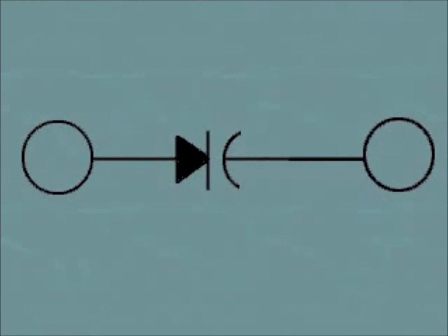If V sub j denotes the junction voltage and K is a constant, which is 0.333 or 0.5 depending upon the manner in which the PN junction is fabricated, then junction capacitance is proportional to V sub j to the power of K. Hence, the PN junction under reverse bias acts as a voltage-controlled capacitor. When a PN junction is used in this mode, it is called a varactor. The symbol for a varactor is shown in the illustration.